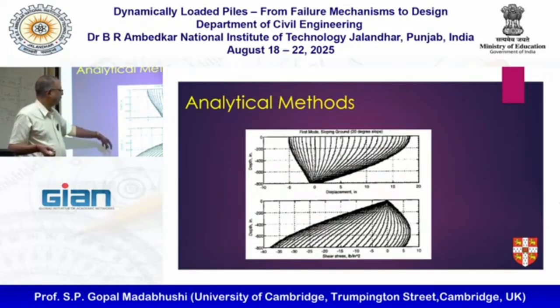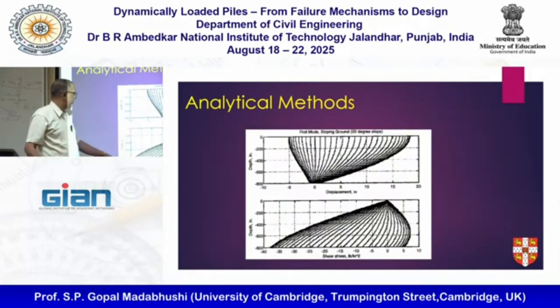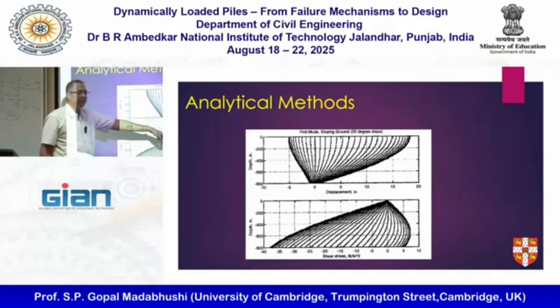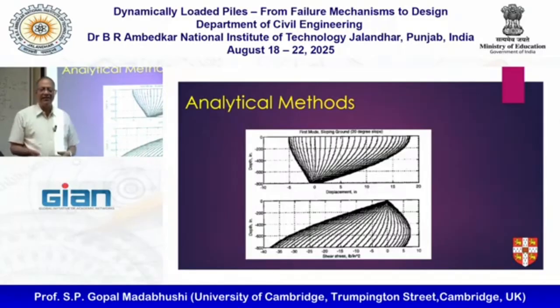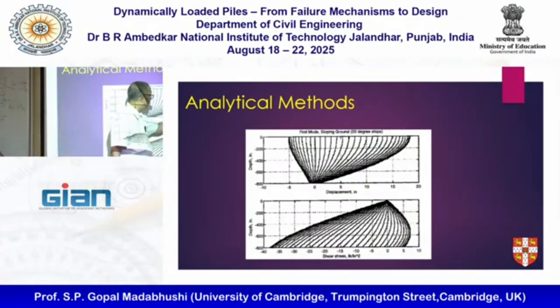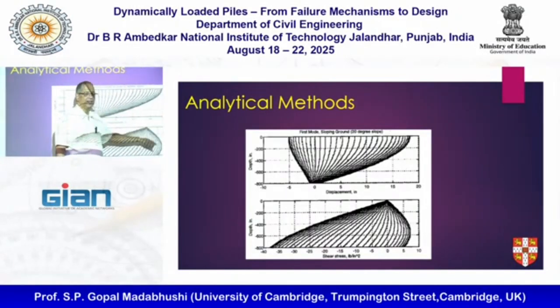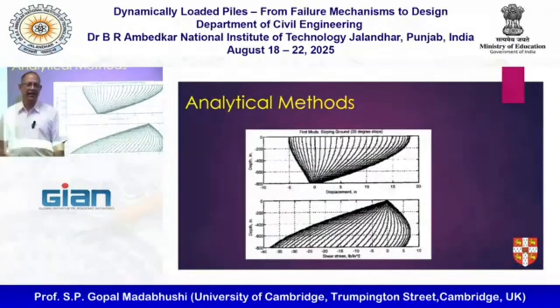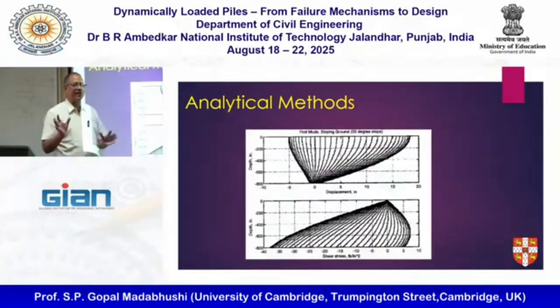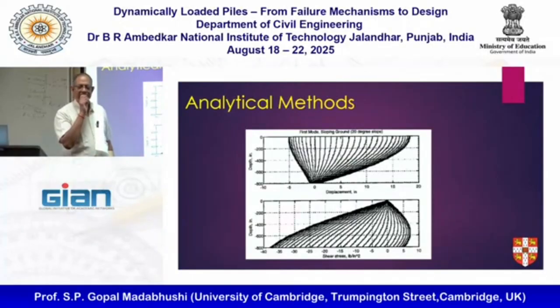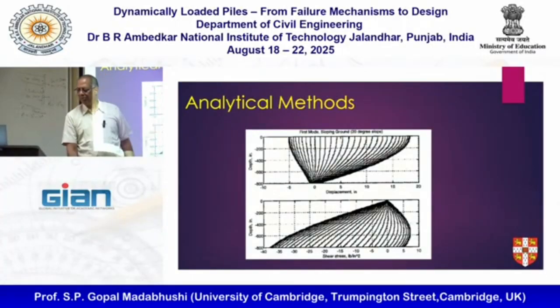And again, you can see how the shear stress is more when it's trying to go upslope, and it drops off. As the soil liquefies, obviously, the shear stress will become quite small, and that's why it's flowing. So this is quite right that at the end of the shaking, I got very little shear stress in the layers. Does that make sense? Yeah? Okay, anyhow, these are the plots one can get.